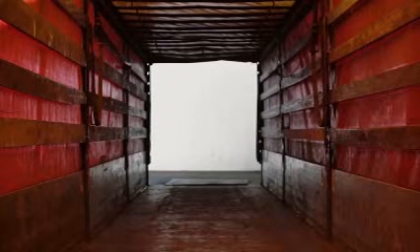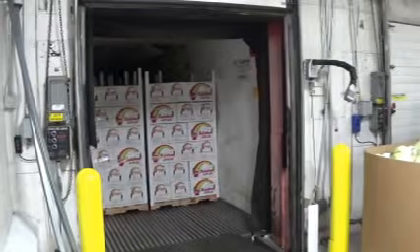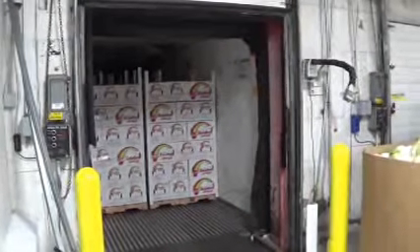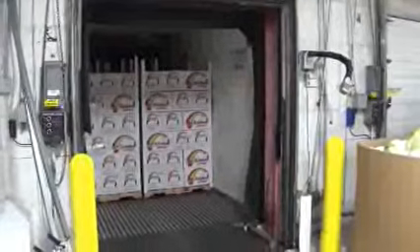Before driving a forklift onto the flooring of trucks, trailers, and railroad cars, check for breaks and weakness. Often, older box cars and trailers have unsafe flooring. Ensure the height of the entry door is adequate to clear the height of the forklift, taking into consideration the height of the loading platform.